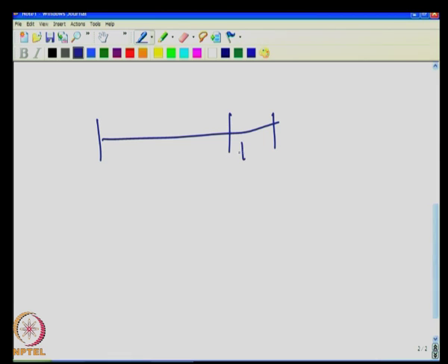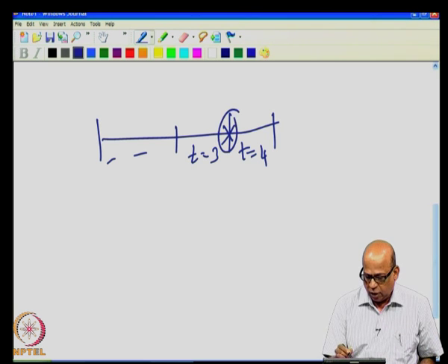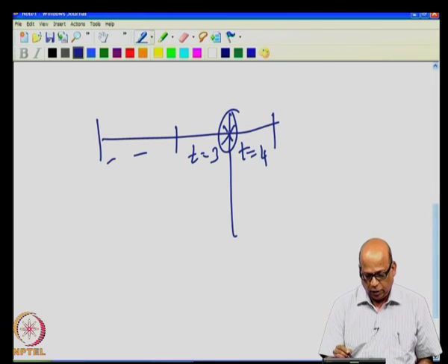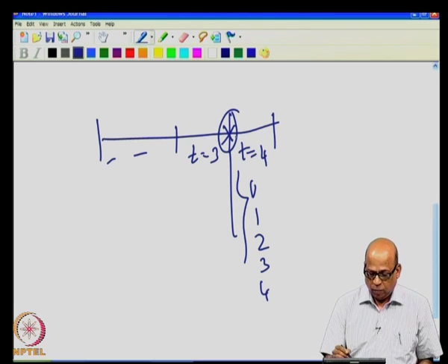Let us say t is equal to 4, t is equal to 3 and so on, like this we went. What we did was, we started the computations at this point, this was stage number 1. So, we said the storage at the beginning of this time period is known, or we solved it for various values 0, 1, 2, 3, 4 etc. for the storage at the beginning of this time. We did not worry about what is the resulting storage at the end of that time period.